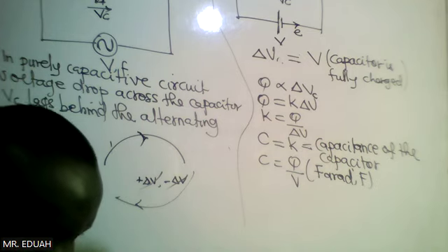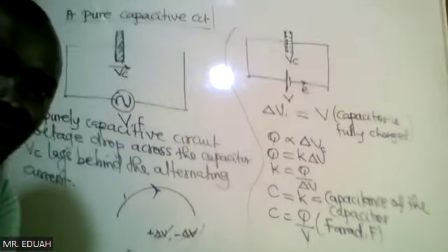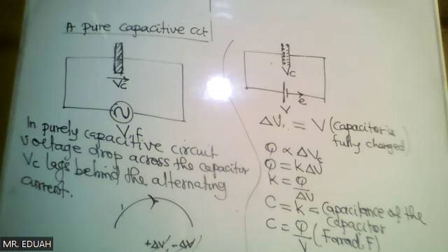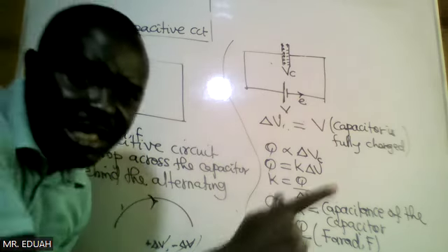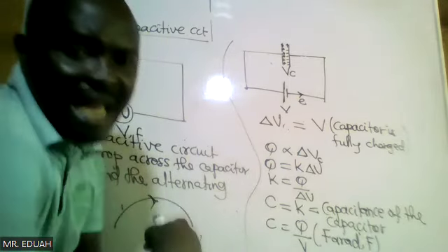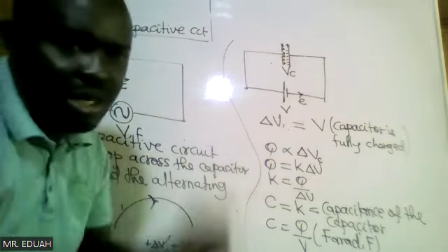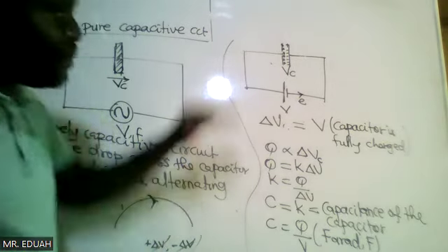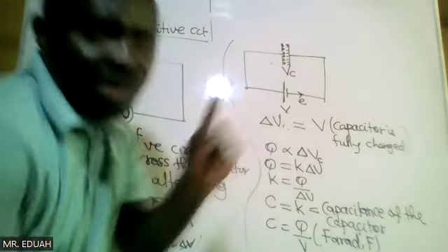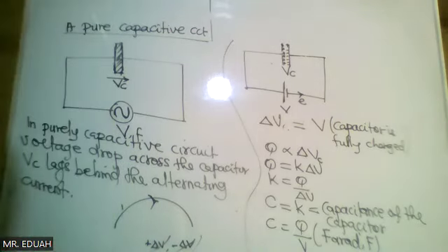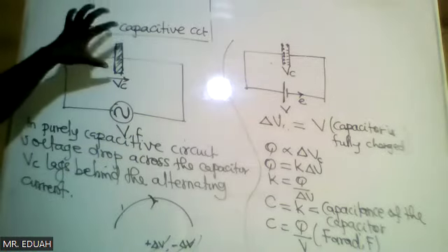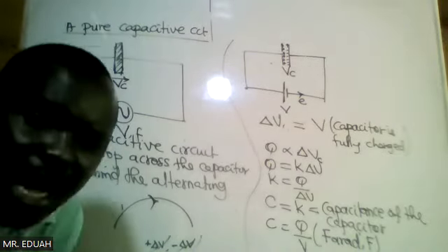So the capacitor gets charged in one cycle and also gets discharged in the other cycle. That is why if you use DC, because of the one directional flow, it will just charge during that flow, and there's no other cycle flow to discharge it. So it will be stored. But with AC, in one cycle, charge is stored, and in another cycle, it is cancelled, and so no work will be done. So applying AC to a capacitor, this is what happens.